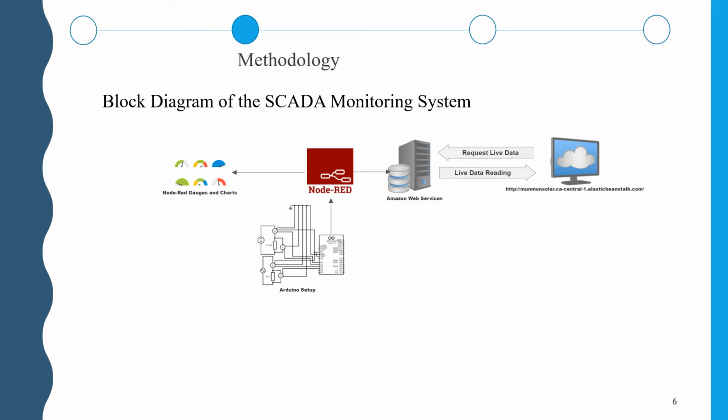As the sensors would take the readings from the PV panels, the readings would be direct current and alternating current. This is done to monitor the power output of the previously proposed hybrid power system for Grey River, Newfoundland, including the PV solar panels which provide DC power and the diesel generator which provides AC power. The Arduino connects to Node-RED and is implemented through the serial port COM4. The real-time data is then displayed through the Node-RED local dashboard and is posted to a web server that can be accessed remotely.